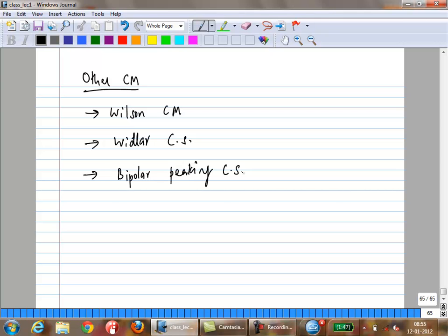Some of them have inherent DC imbalance, like the Widlar, for example. Okay, but I mean it still gives you enough output impedance and so on. Okay, so it's a little bit simpler. And so these things, I mean, they're definitely of interest for certain applications. Okay, so we'll probably not be looking at these in any detail. Probably 1 or 2 of these might end up in your homework. I don't know, maybe just the Cascode. Okay, but since we are going to concentrate mostly on MOSFETs, we'll probably stop with bipolars here.